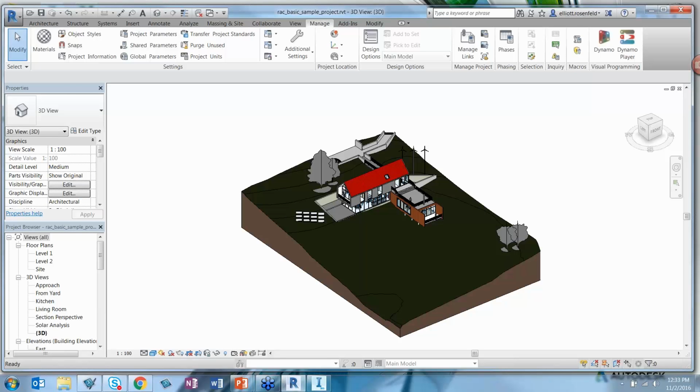Elliot, sorry, I saw a question that somebody was asking about the Revit materials coming across using the RVT file. That was one of the main reasons I set up that Navis view from 3D view. I found that if you export the 3D view and do a save as, if you have custom textures, they typically will not come across, but if you set up that Navis view, Navis will look for that first, and it does a really good job of bringing even customized textures across with your RVT file. So if you forget that step, make a 3D view, call it Navis, and then save as again, and it should bring all those materials across.